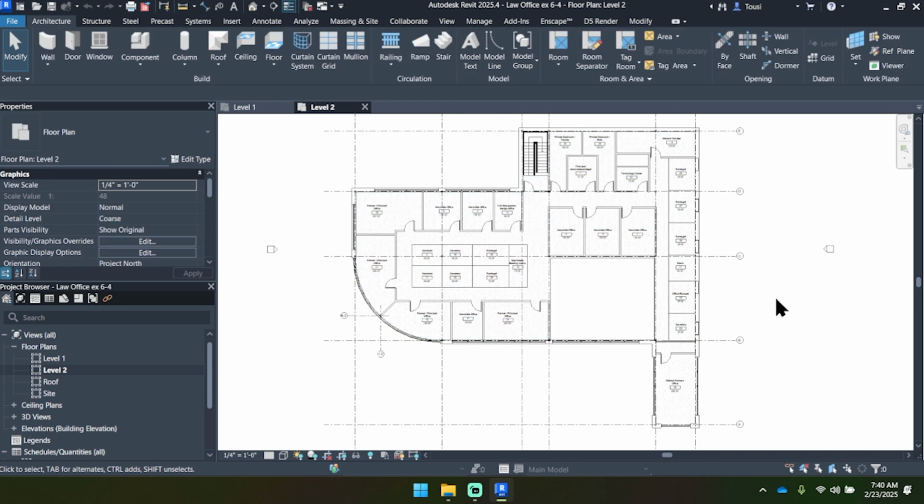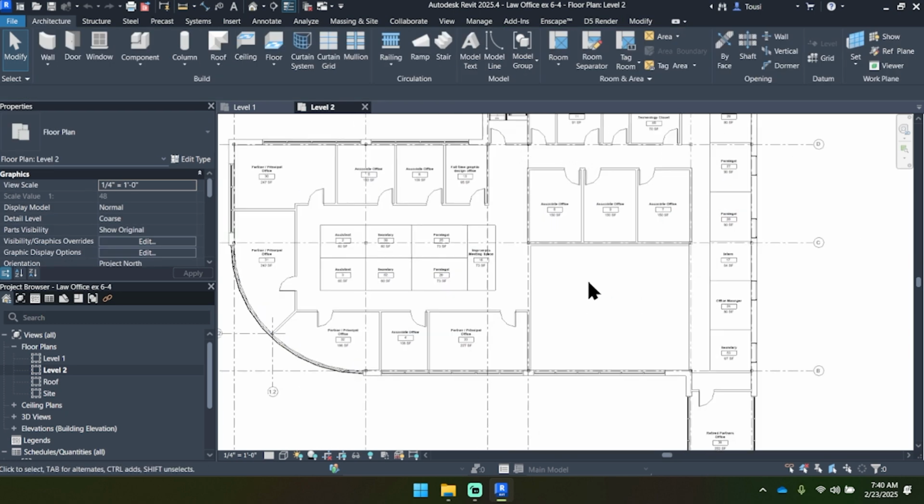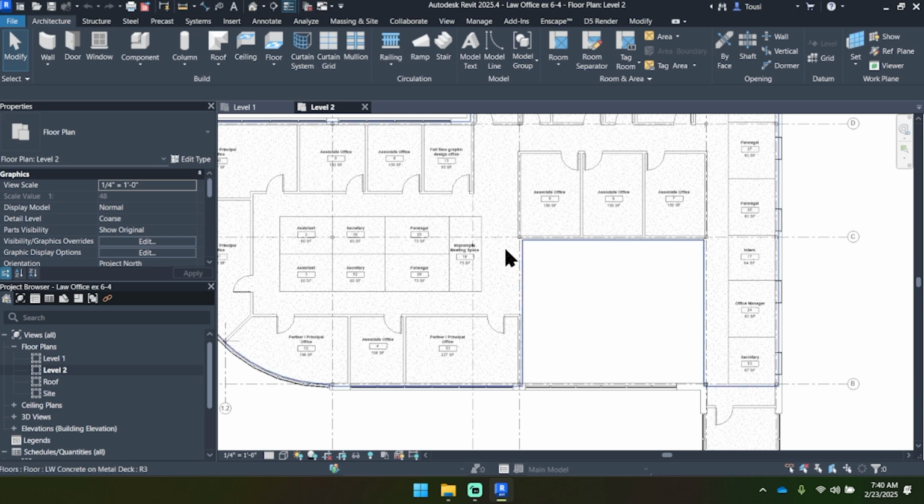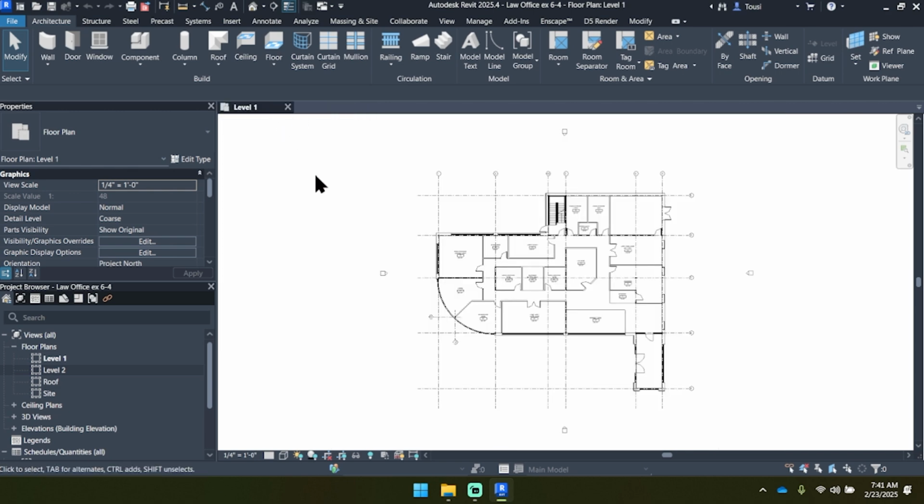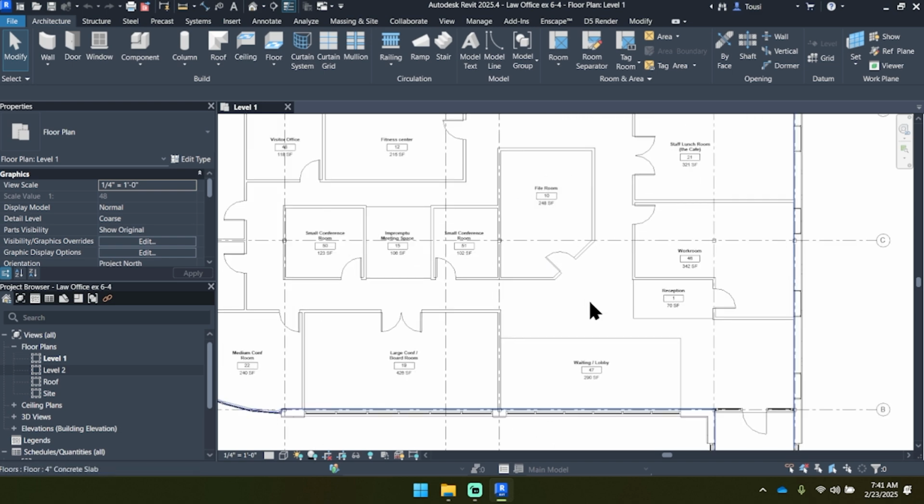Also along the way, we're going to be updating this stairs assembly so that the stringer on the sides of the stair match up with the floor type for the second floor, so that they architecturally work well together visually and likely installation wise. So getting started on 8-39, on level 1, we're going to start by drawing some detail lines so that we can orient the location of our stair and not just start throwing it in and guessing where it's going to be going.